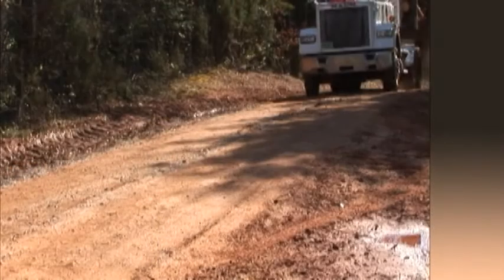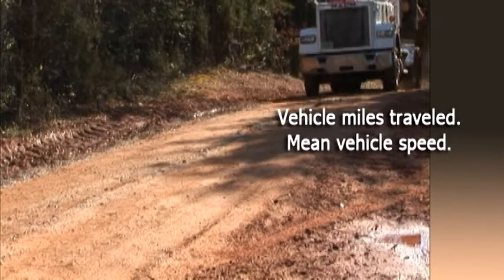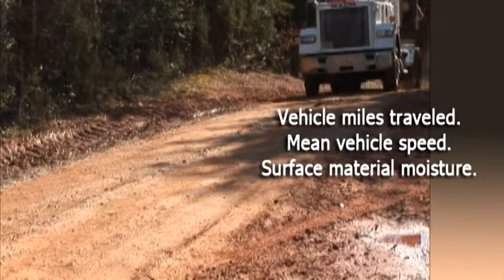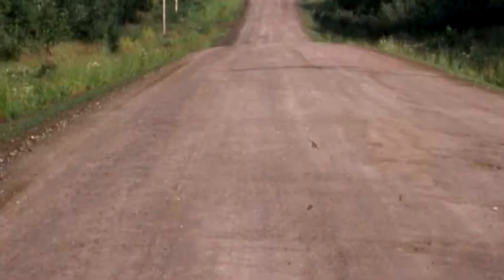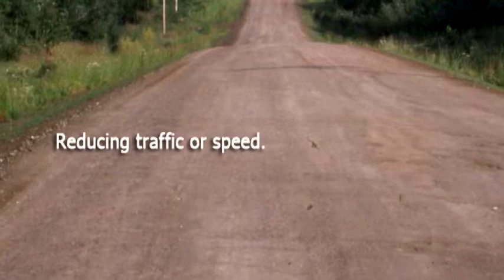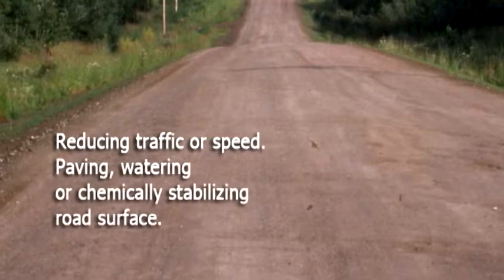What affects emissions from unpaved roads? Well, vehicle miles traveled and vehicle speed affect emissions. Also, the moisture and silt content of the road surface material is important. What reduces the emissions from unpaved roads? We can reduce traffic or the speed of the vehicles traveling on the roads. We can water or pave or chemically stabilize the road surface.